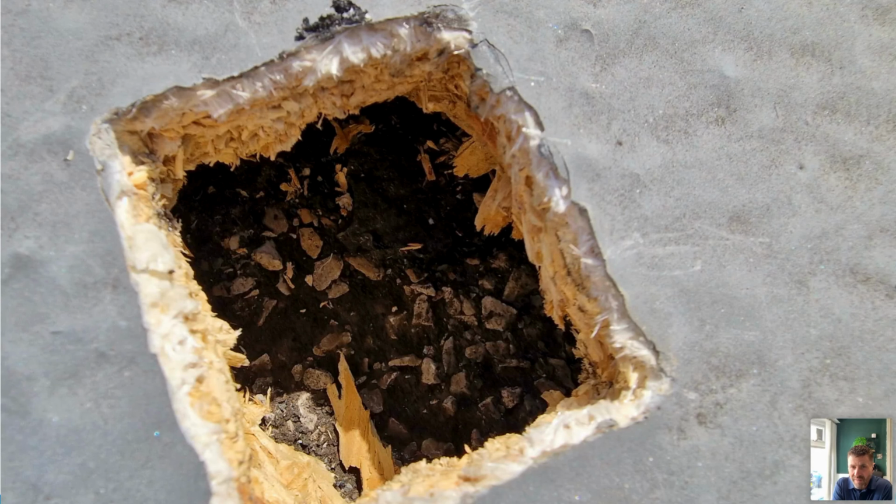So we need to remove a larger area now and take a core sample of that deck below, so that we can do the right U-value calculations and the right condensation risk analysis, to make sure that we're putting forward the right specification for an overlay on that roof. Does the GRP system need to come off? Is it causing interstitial condensation? All of that kind of stuff.